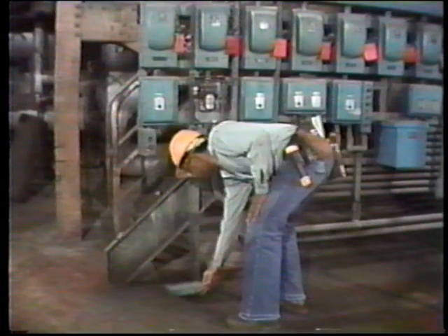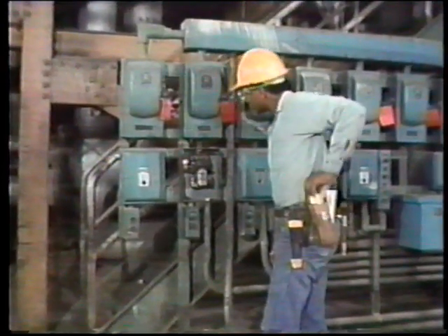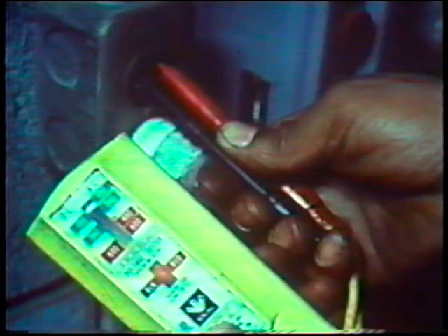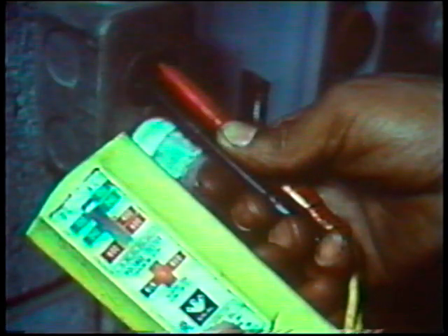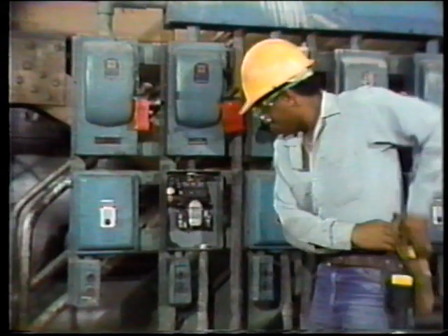Bill checks the electrical equipment to see if it's been de-energized. It's already been tagged out and the switch is off. Bill checks his voltage tester on an energized source to be sure it's working. Now he tests the circuit, phase to phase and phase to ground. Finally, he checks the voltage tester again to be sure it's in good working order. Okay, he knows it's safe, so he'll go on.